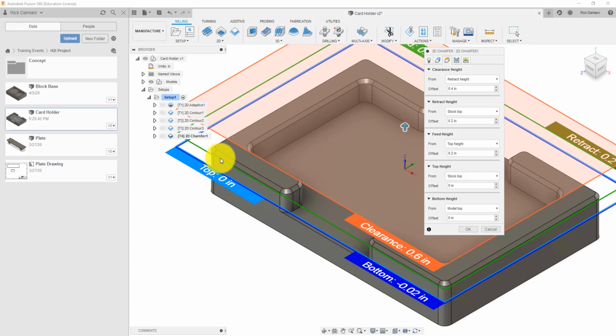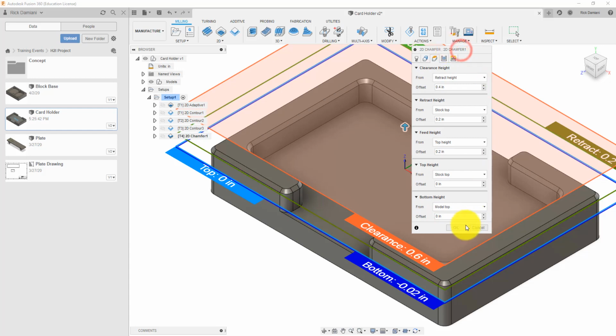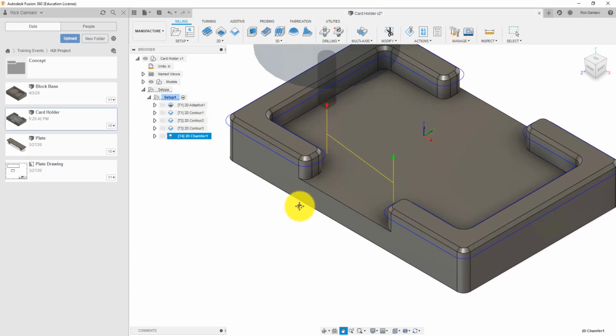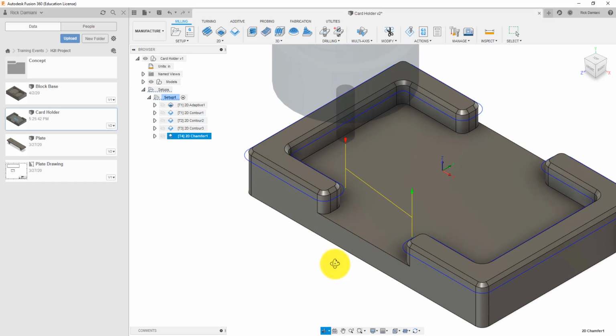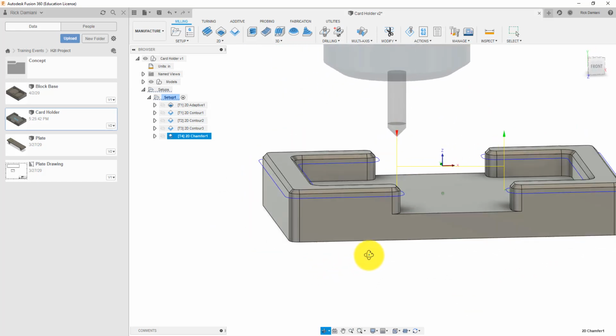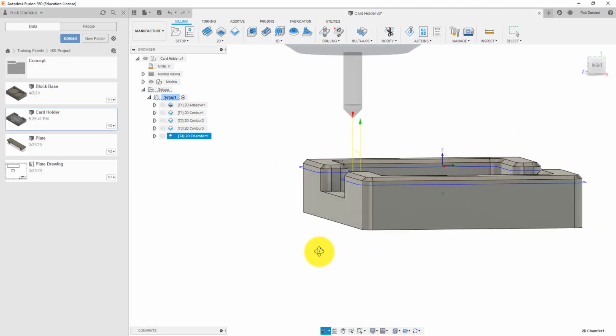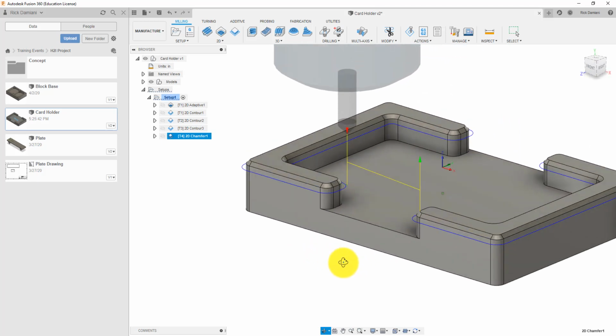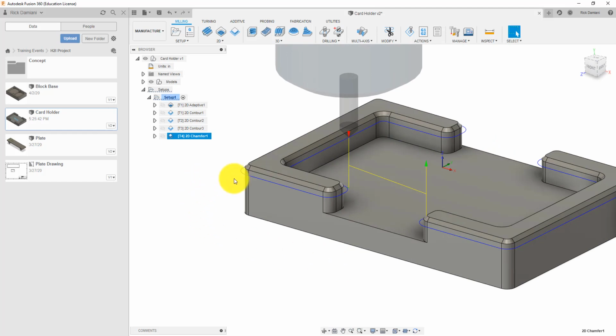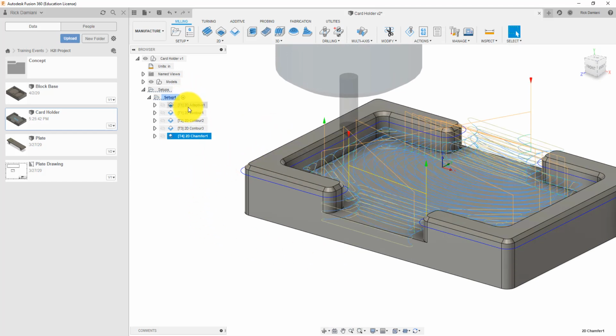So the chamfer depth is going to be calculated from the contour. The contours in the chamfer extents, the chamfer shape, are going to be the shape that I picked. So this is actually going to have us at the apex, the theoretical apex. Okay. So select OK. And there's my chamfer toolpath. A little concerned about that, but it should be okay. It looks like it's 100 thousandths down. It should be right. And oh, last thing, I almost forgot.